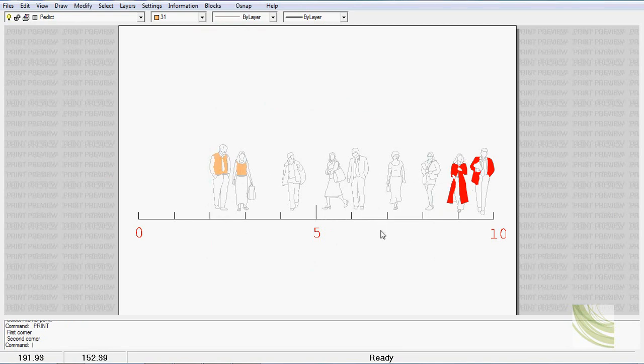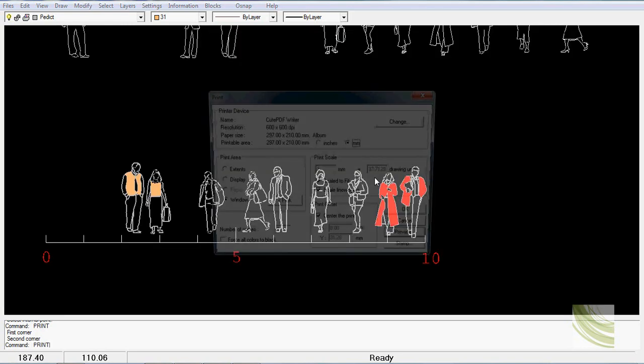We haven't colored any of these yet, but I hope you'll agree that if we print that, that can become a graphic. I think the contrast between the black of the scale and the figures is a little too great, so we could simply change the color of the layer there and improve the graphic. But you don't have to, that's the whole zone. Let's hit the escape key.